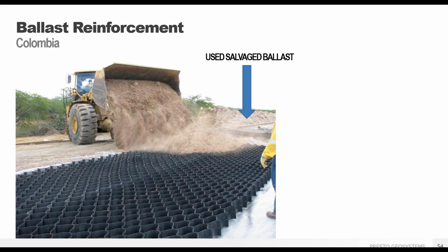They did go ahead and basically remove all those prior to putting the ballast layer in. But if we can have a material less than about 15% fines, we can use that for a GeoWeb infill. So on this job, like I said, it was about 10 miles of track, 6-inch GeoWeb. They saved about 16,000+ yards of material. So you can imagine how much of a cost savings that was.